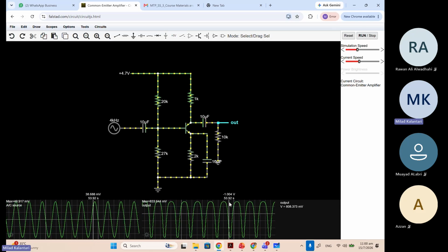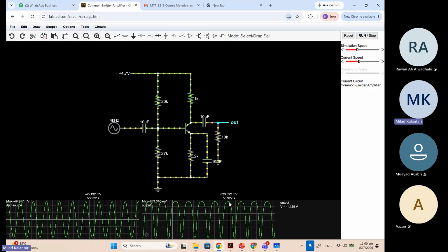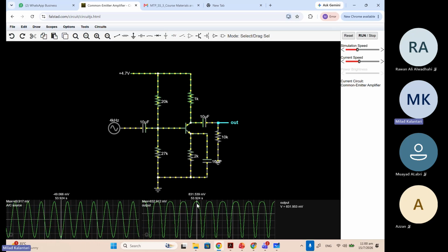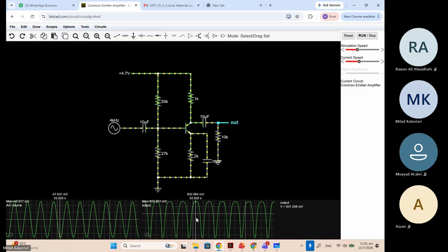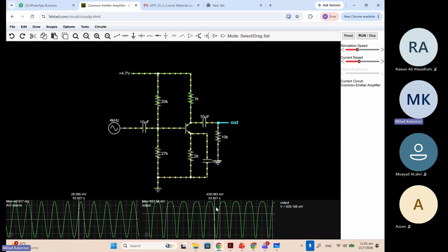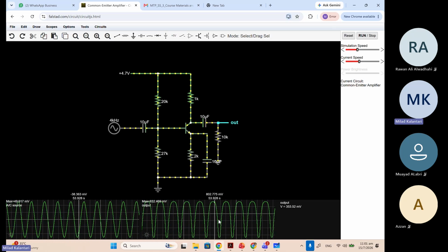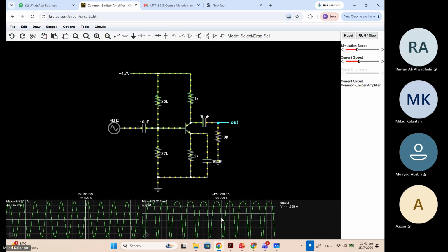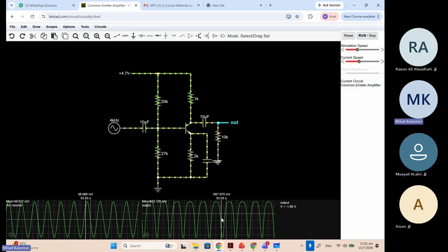So the linear circuits and systems, right? You expect just multiplying the input by something. It doesn't change the frequency content, basically, right? The linear systems just multiply it or phase shift it, right? It doesn't change the waveform. But now you are seeing the waveform is changing, right? The waveform changed because the frequency content of this output is changed, because there is some nonlinearity, right?